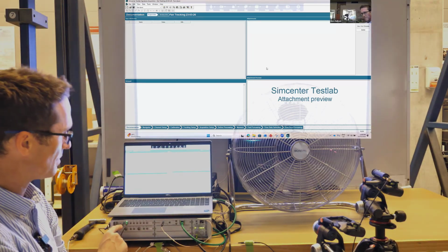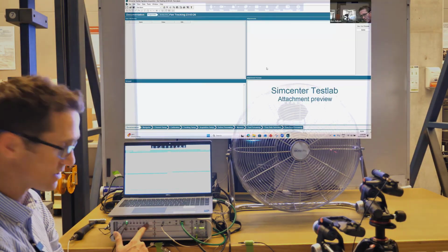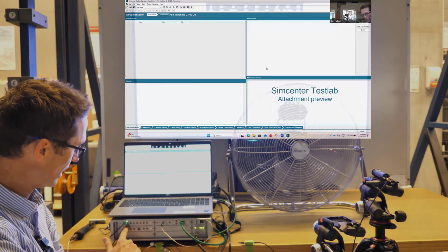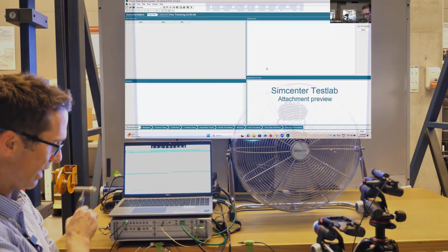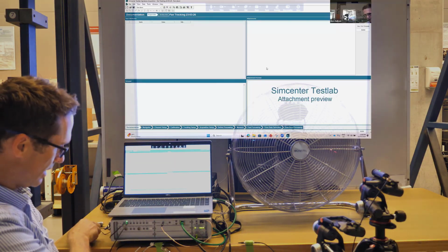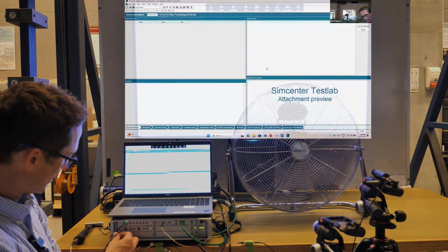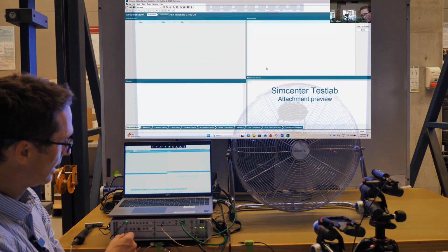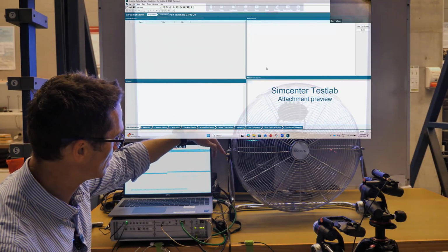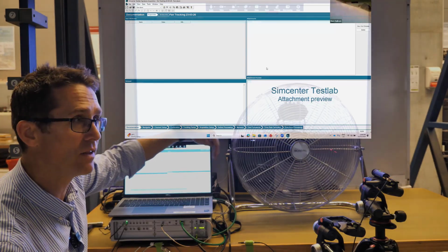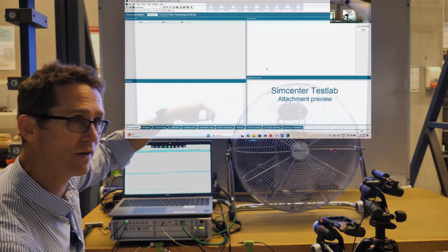I've got 2 other channels connected to this V8 acquisition module here. These are vibration channels, volts and IEPE. On one of those channels I've got an impact hammer, a modally tuned impact hammer, and I will reveal why in a few moments. That is connected onto channel number 1 over here, and on the other channel, channel number 2, I've got an accelerometer which is currently mounted to the frame over here of the fan, and that can measure the vibration of the frame as the fan rotates.